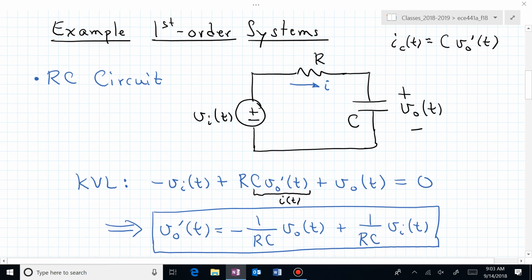If we solve that now for the highest powered derivative, which is just a first order derivative, we can push everything over on the right hand side, and with this particular representation of that first order differential equation, now you might be seeing a block diagram, an all integrator block diagram. If not, maybe you should. But no, it's just another way of thinking about a first order system.